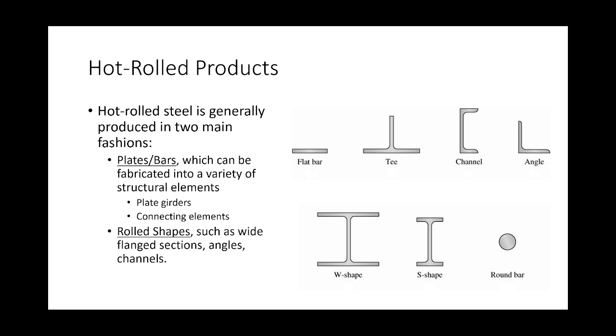So if you have a shape that's a W10 by 49, the 10 is about how deep it is. If you look at this handout I gave you, you'll notice that most of the shapes on this handout are W12s. And so, barring the ridiculously heavy ones, most of these depths are about 12 inches. They're not exact, but they're pretty close to 12 inches. Do you see that? Again, barring the super heavy ones.